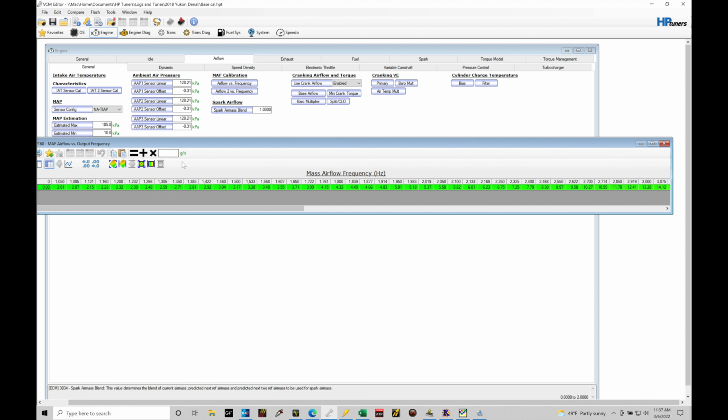At idle, where the throttle is fixed and relatively steady, the sensor has a great signal. Cruising on the highway at 65 or 70 miles per hour, it's a great registration of airflow. And at full throttle, even though airflow comes in quickly as engine speed picks up, it's still a relatively steady state condition. In any steady state condition, the mass airflow sensor is the preferred way for the engine control module to reference the airflow coming into the engine.